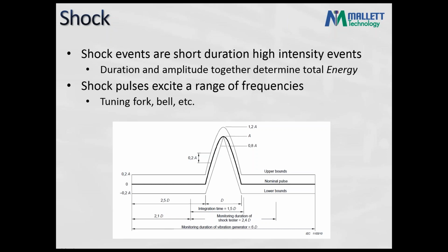And the second thing I want to note on shock is that shock pulses excite a range of frequencies. So if you think about a tuning fork, when you hit that against something, it's not exciting just the frequency the tuning fork vibrates at. It excites a range of frequencies, and the natural frequency of the tuning fork picks up that input and then amplifies it, and so that's what it vibrates at.